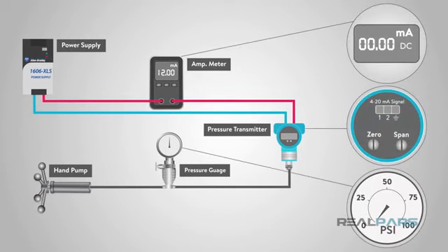If we have an analog transmitter, we must adjust 0 and span to reduce the measurement error. With an analog transmitter, there is a 0 and span adjustment on the transmitter itself. 0 adjustment is made to move the output to exactly 4 milliamps when a 0% process measurement is applied to the transmitter.